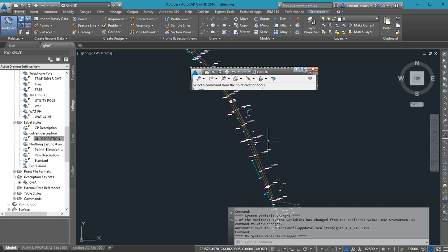But if we have an existing road and you include the river, when it gets to where the river is, there will be a drop. You understand? But that's not what you want, your interest is the road. If there's no existing road, then we want to see the river in the cross section and put it in our profile. I don't know if you are getting the picture.